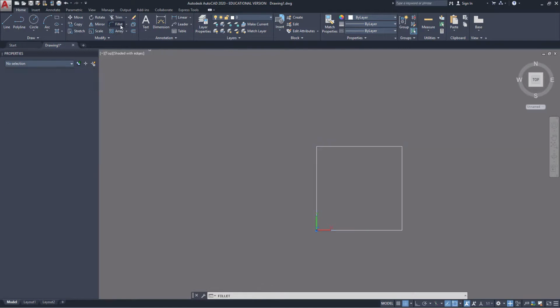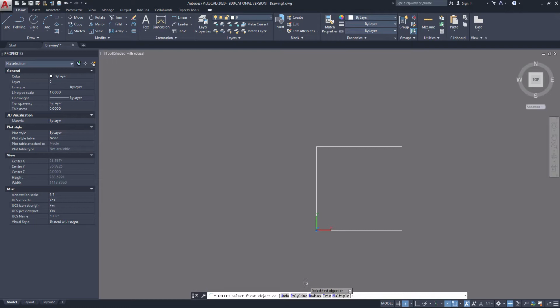I'm going to use my fillet tool. The fillet, I'm going to click down here at the bottom. I'm going to set the radius. I want the radius to be 12 millimeters or half an inch. And now I can click on this corner, or that line there, and then enter again. Remember, the enter key is a redo last command. So it's fillet, so click on those two, enter again, click on that one, enter again, click on that line and that line. And so now what I've got is my object which has got the corners radiused off.